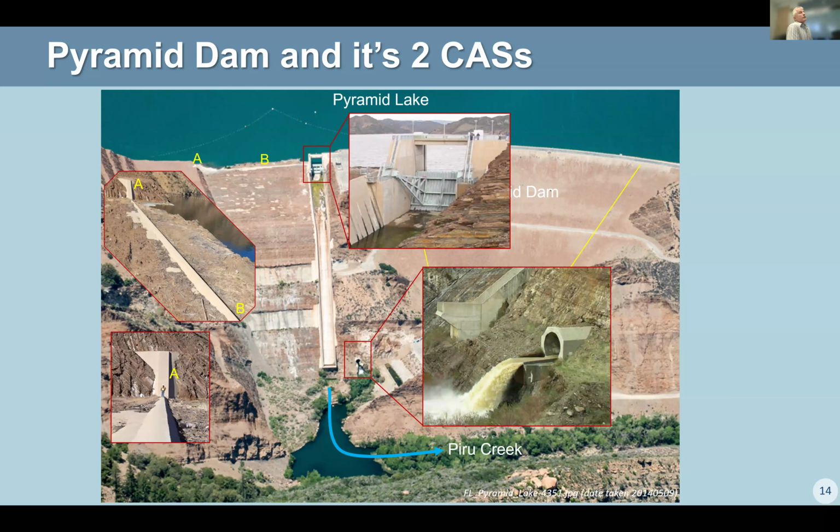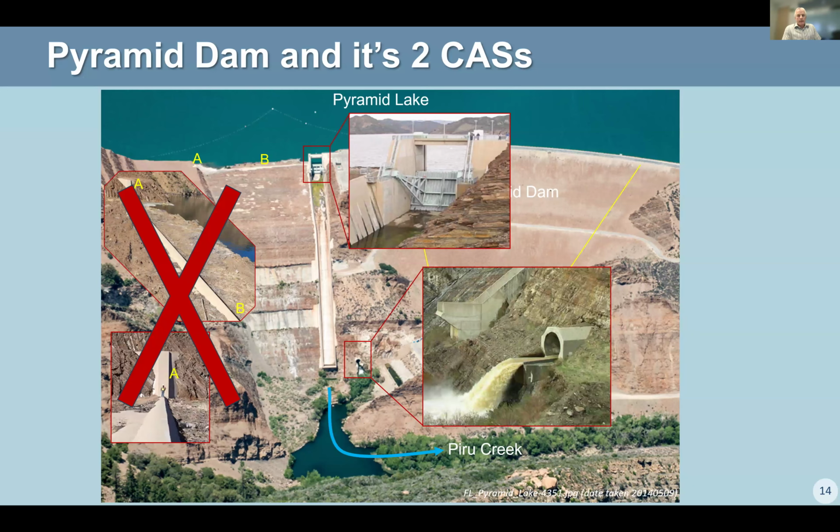This dam also has an emergency spillway, which is basically a weir. It's an ungated spillway, and water could flow over that if there was a very large hydrologic event, a storm. But this weir itself is only like 4 feet high, and it doesn't impound 5,000 acre feet of water, so we don't have to make a map for that and put it in the emergency action plan.